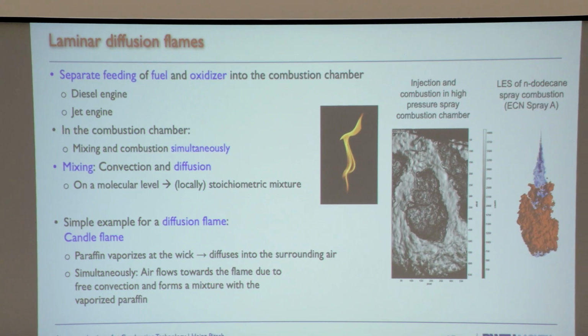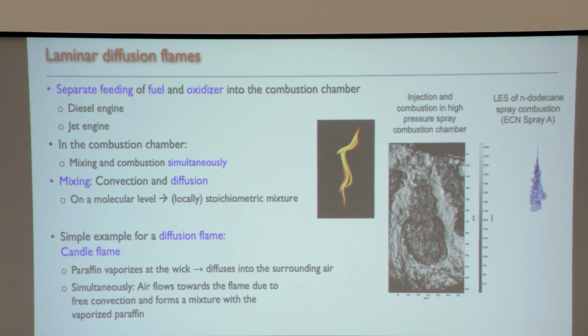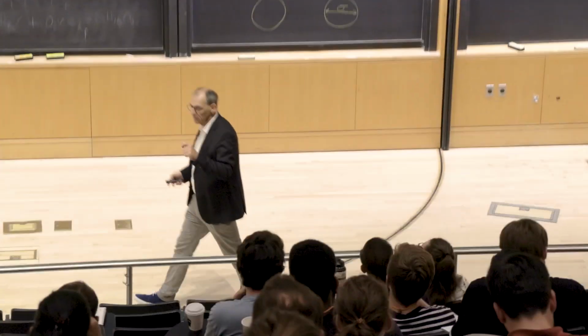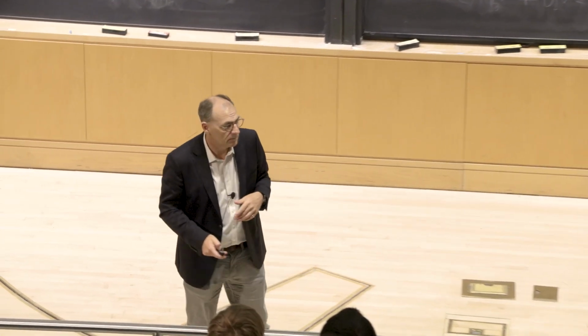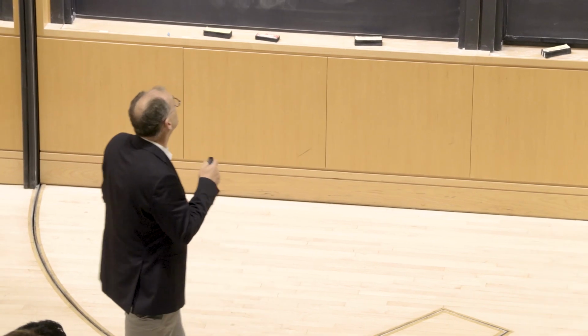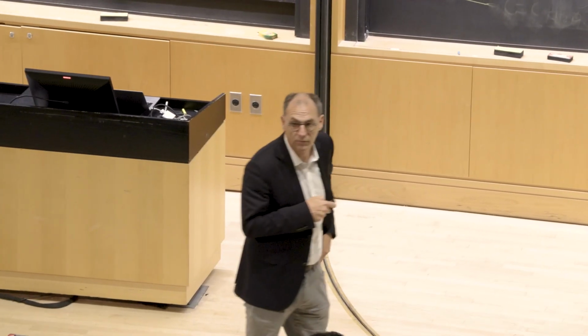In a jet engine, we use non-premixed combustion typically for safety reasons. I showed you the non-premixed flames are much more stable than premixed flames, so that makes it a desirable feature for jet engines.